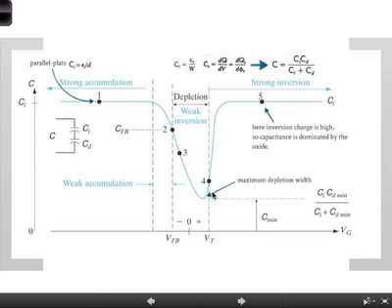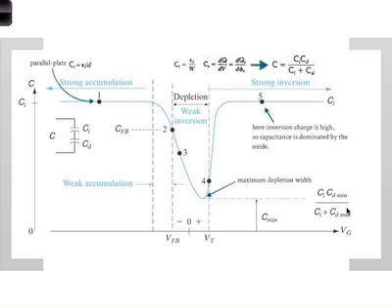Okay, so beyond that, the depletion width really does not increase, which is why the capacitance starts increasing. Okay? And then you can calculate this. If you can measure it, it will allow you to experimentally determine what the acceptor concentration of the p-type substrate is, which is otherwise hard to do, as you can think about.